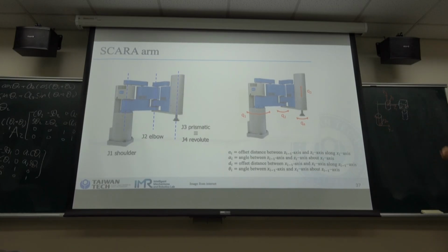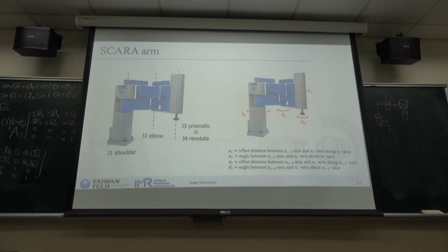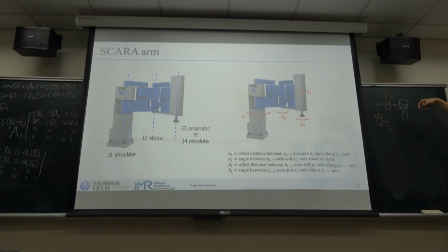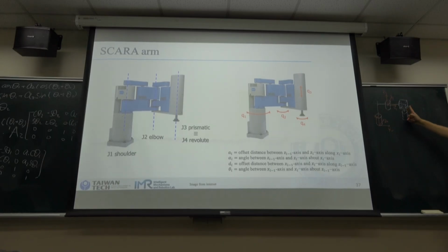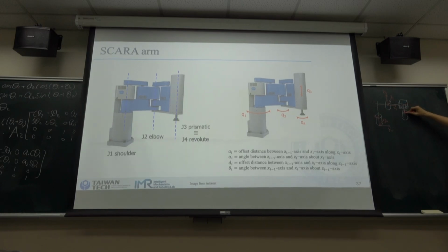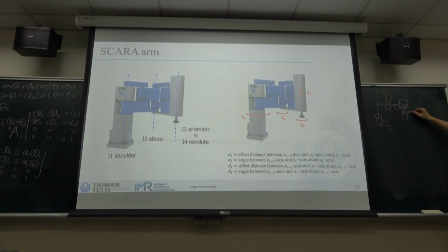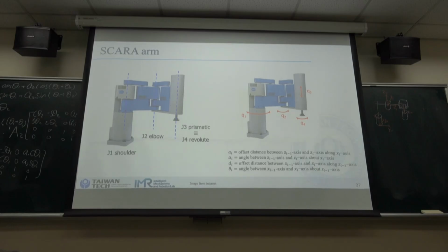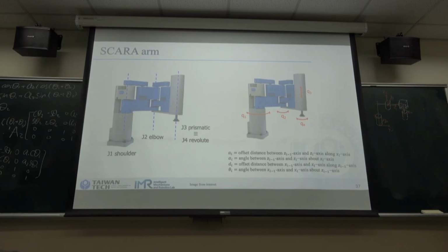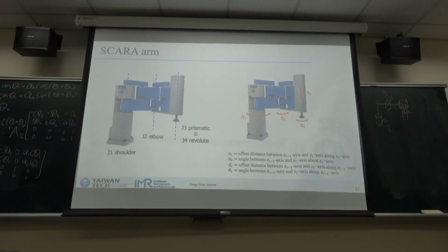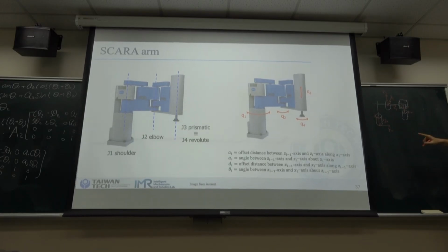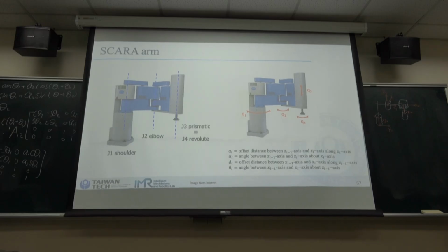And for the third one, we know that the z-axis must be in the direction of the motion of the joint, so whether you want to go up or go down. Here we choose going downwards. So this is z2. And we know that the x should be perpendicular to z2 and z1, so we set it in the same direction, here at x2.